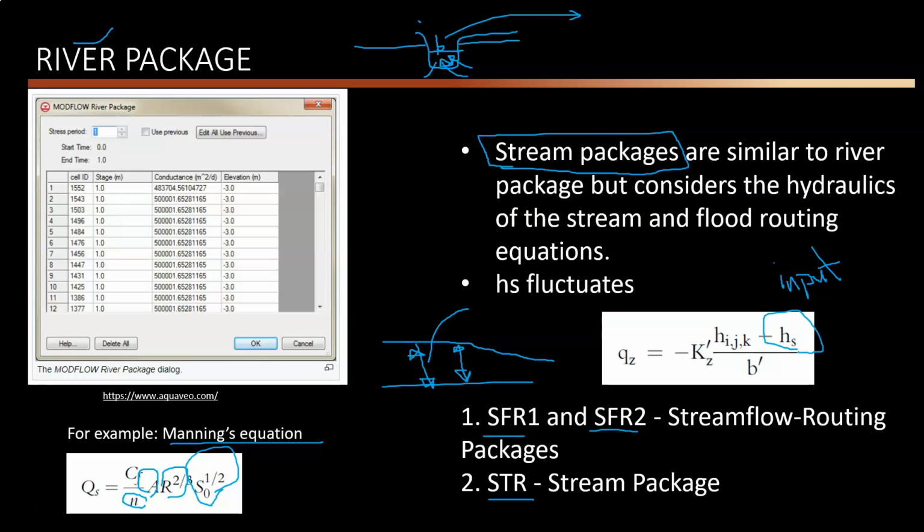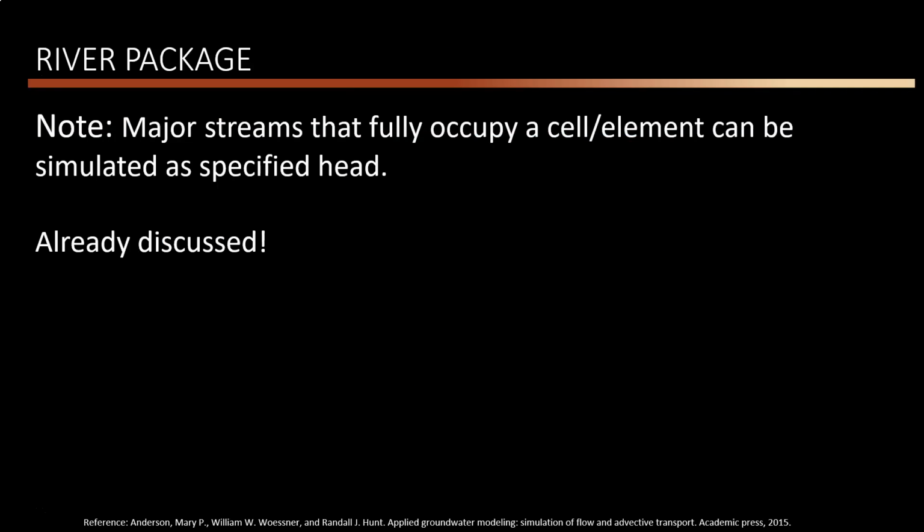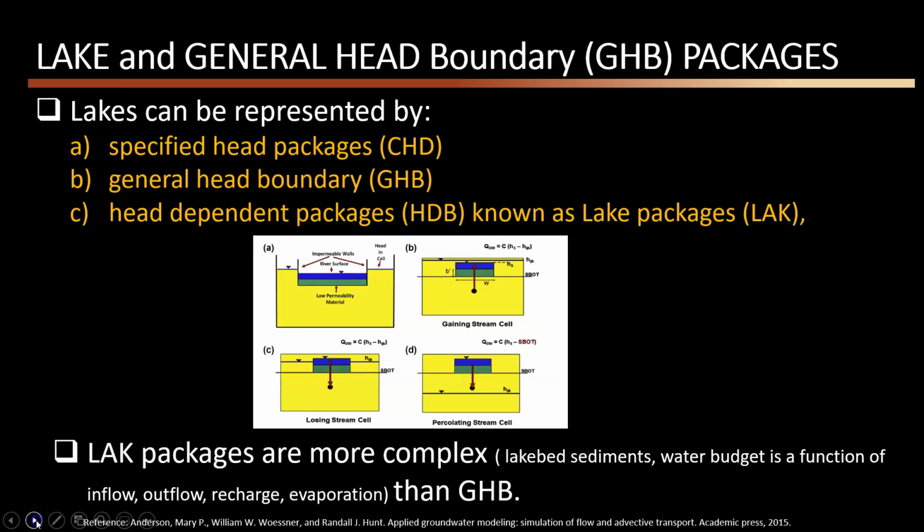The stream packages. Again, as we already discussed, you know that you can model or simulate streams using the specified head package as well, but we usually try to avoid that for the reasons we already talked about. We better simulate them using the river package or stream packages rather than considering them as a specified head condition.